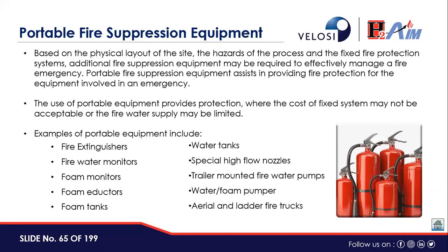Next question. Using foam extinguisher on LPG, is it correct or wrong? See, on LPG, it depends on if you're doing LPG spheres, right? Mostly it's cooling, and foam should be thrown on a surface which can isolate the area. And normally on spheres, foam is not effective, right?